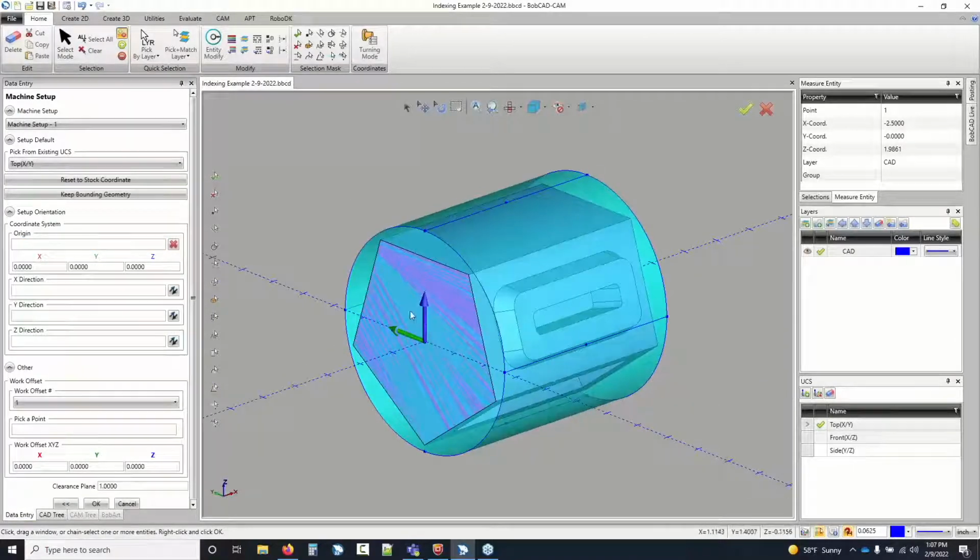Now, I like to set my origin in the center of the rotation. I'll find X and Y right here. I'll find Z, and then I'm going to drop down whatever the radius of that stock is. That's how I always like to find my origin for this. So I don't actually have anything to change because of how I situated my part right on XYZ0. There's nothing that I even need to modify.